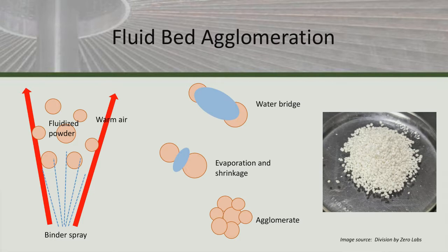And when you put a slug of this in a glass of water, for example, there are cracks and void spaces that water can diffuse through. So it's actually breaking the surface tension, even though the density really hasn't changed. It's more the shape that causes this to happen. On the right here, I have an image of spray dried particles that have been agglomerated.